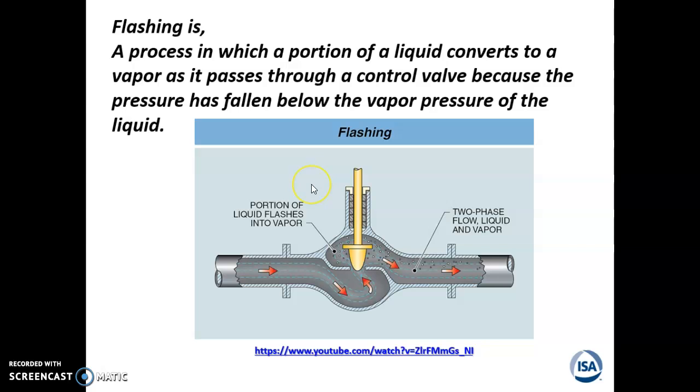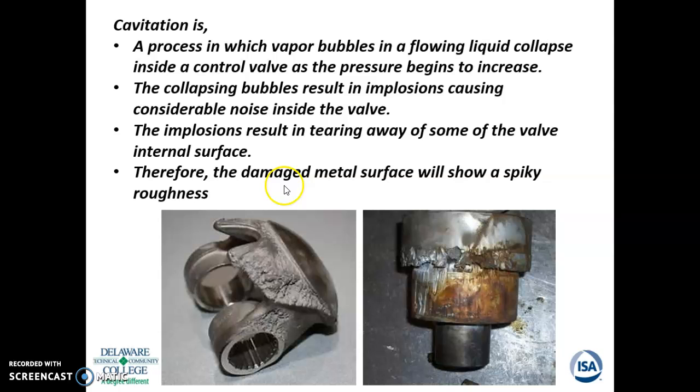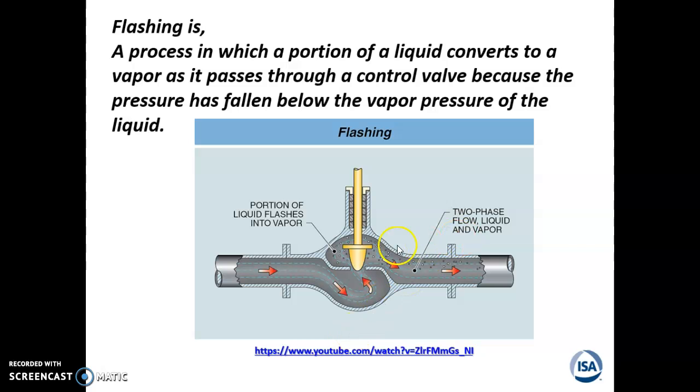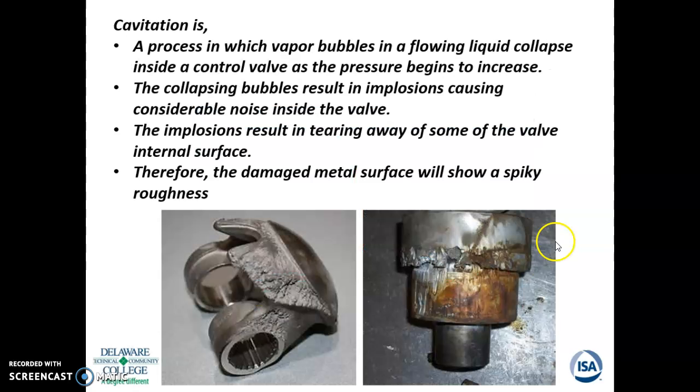Now, I want to talk about some of the issues that can happen with the valves. You can have flashing, and this is a good video talking about that. It's just when a portion of a liquid, if you have a liquid stream, converts to a vapor. Very similar to what happens with pumps. You can have the flashing in the pump, and then they all result in cavitation, okay? In a valve, it's really amazing how it will damage the valve and the materials of construction. It's actually pretty crazy.